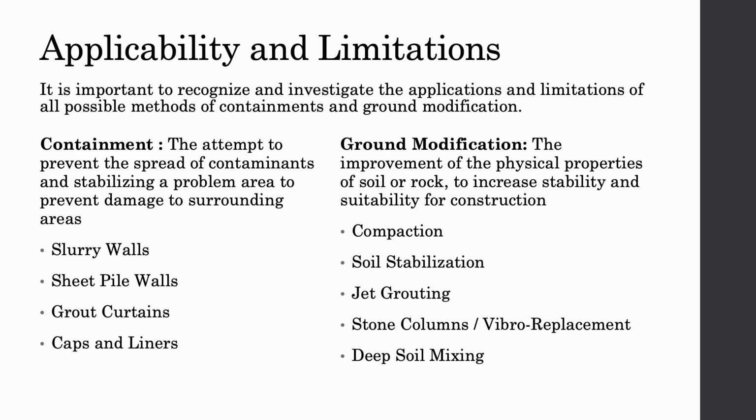Ground modification can be defined as the improvement of the physical properties of soil or rock in order to increase stability and suitability for construction. This includes compaction, soil stabilization, jet grouting, stone columns and vibro replacement, and deep soil mixing.